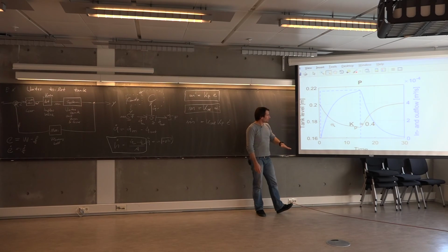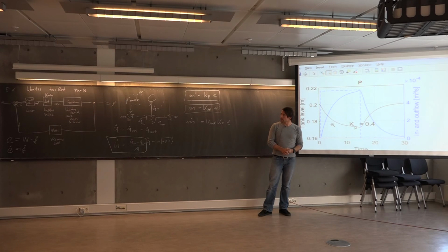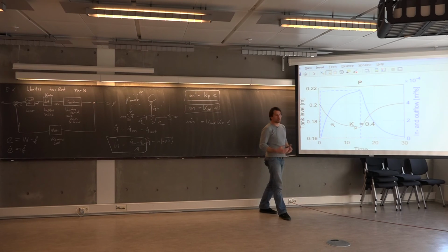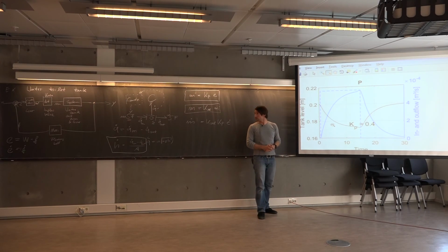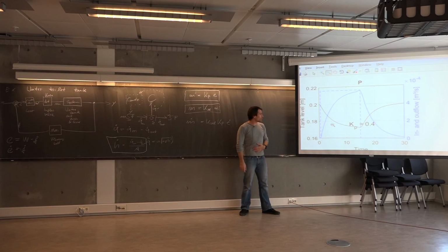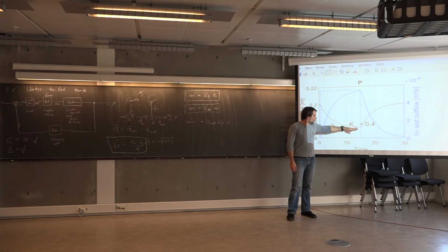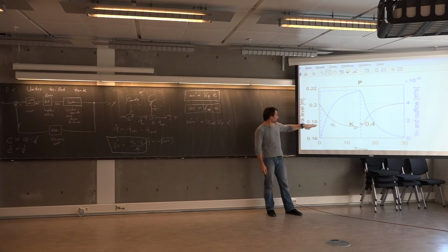The tank level decreases. And if we haven't had any controller, it would just decrease continuously until the water tank is empty completely. But now we have this controller in place. And using a numerical value of 0.4 for this Kp factor in our controller equation, we actually managed to level out the water in the tank at something like 0.17 meters, 17 centimeters.